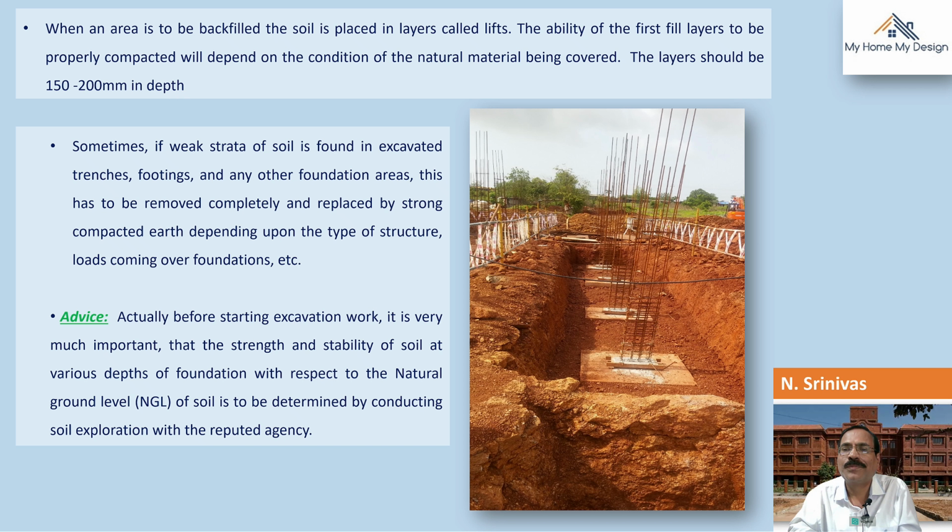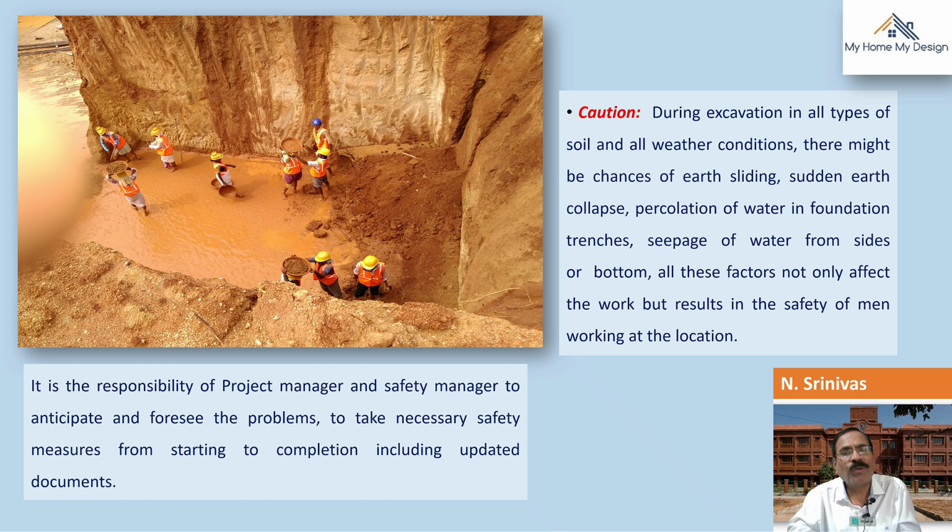Suppose if you do not follow those terms, what is going to happen during excavation in all types of soil, loose soil as I told earlier, and all weather conditions, flood seasons? Normally in Bangalore, June, July, August, heavy rains are going to happen. At those times, what is going to happen? There might be chances of earth sliding, sudden earth collapse, percolation of water in foundation trenches, seepage of water from sides or bottom.